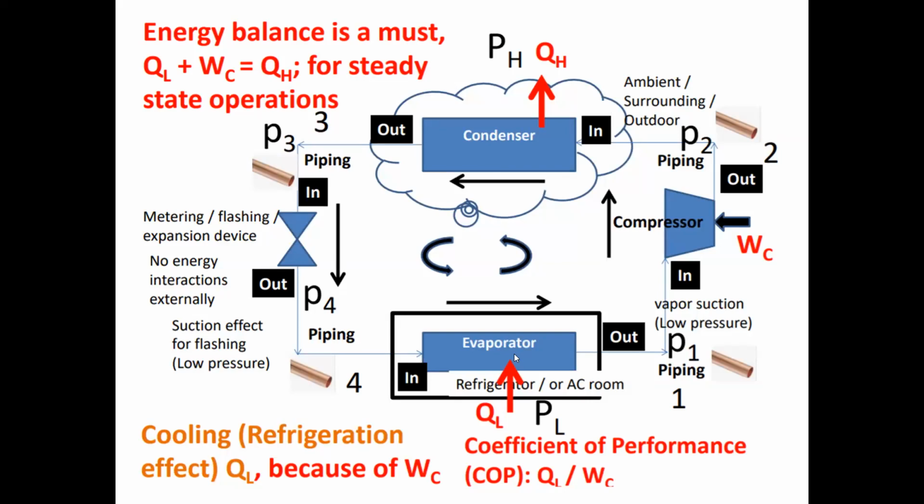That's the refrigeration effect. And your performance is the heat received at low temperature that is pumped out, against the system work input that is provided to the compressor. So the compressor is really the component that makes this flow of working fluid through the system possible. So the work done on the compressor is actually the work done on this working fluid.